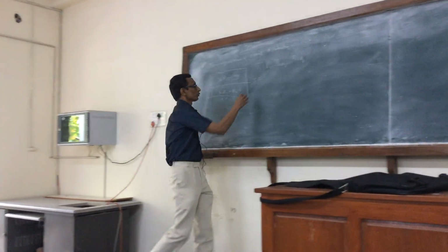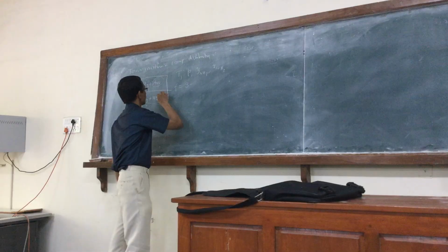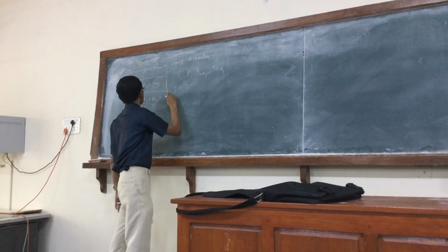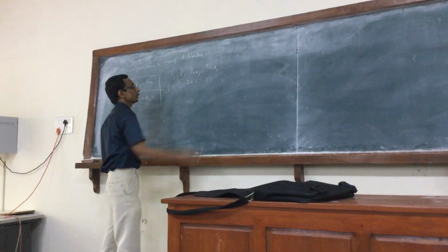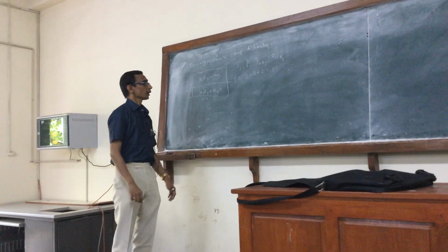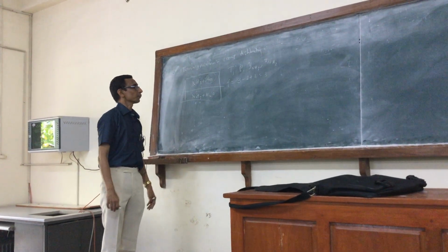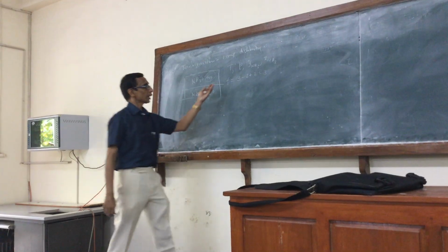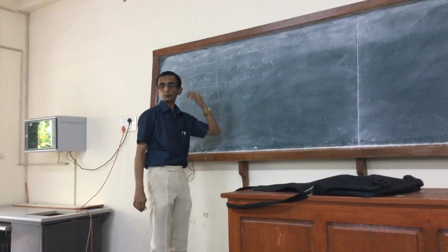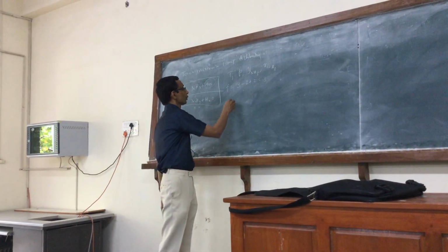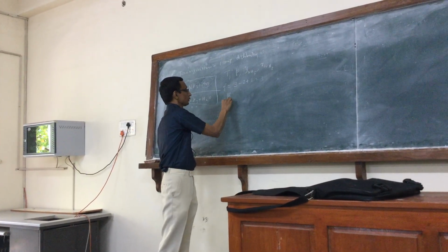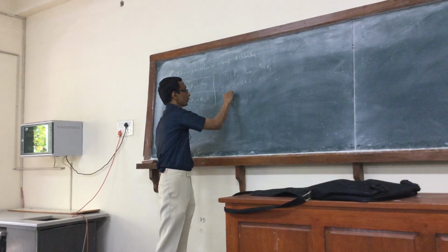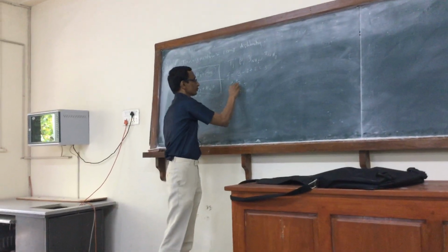So the degree of freedom is now 3, meaning air as one component, minus 2 plus 2 is equal to 3, as compared to 2 earlier, and we have now 4 variables, and so the only equation I have is still the equilibrium relation.